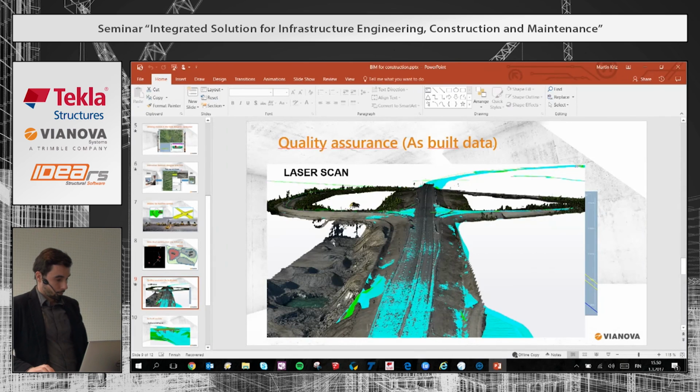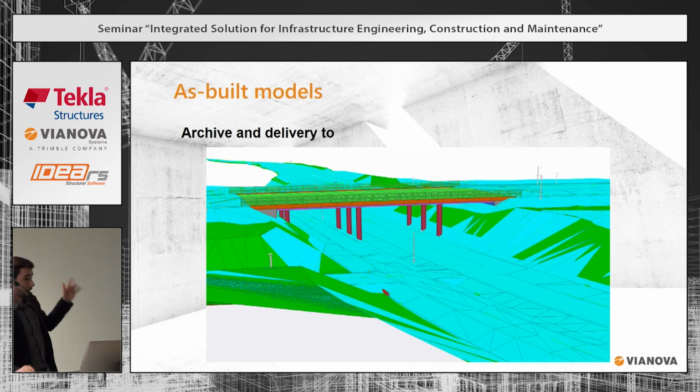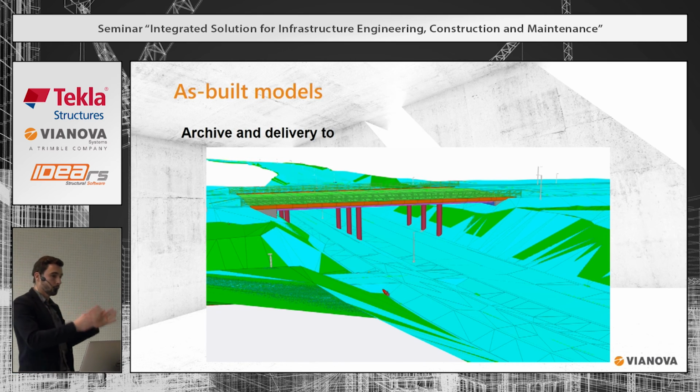What else do I have? Yeah, and then the important thing is when we go to the next level from the construction. So we are collecting the as-built data. So to the database we are collecting also the as-built model. When we are getting the points, the measurements, I keep on building the as-built model, so that when the construction is done, I have the model which I can then publish or give to the authorities for the maintenance.